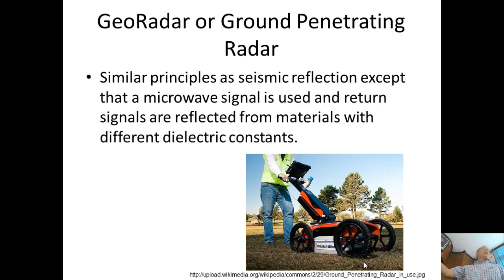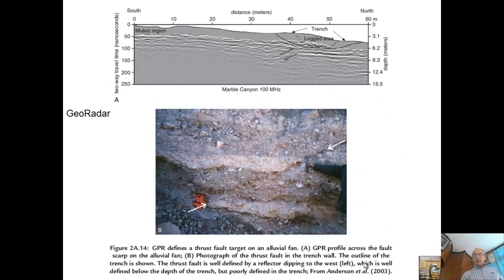And many of you may have done this, but you basically pull it. They have the sensor and the receiver in the same system, so it's just shooting straight down. There's not usually offset type approaches in georadar. And so that's just pulled in a sled slowly, and it's shooting the whole time. And so here's an example, it's 60 meters along this area.